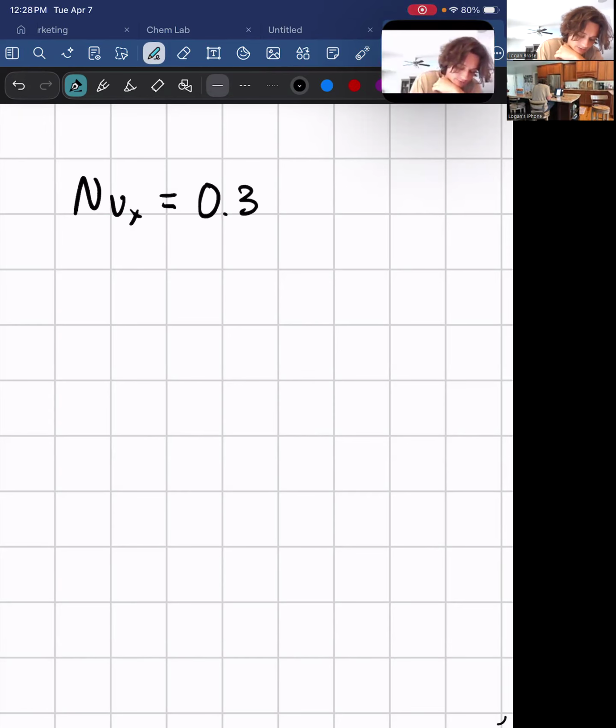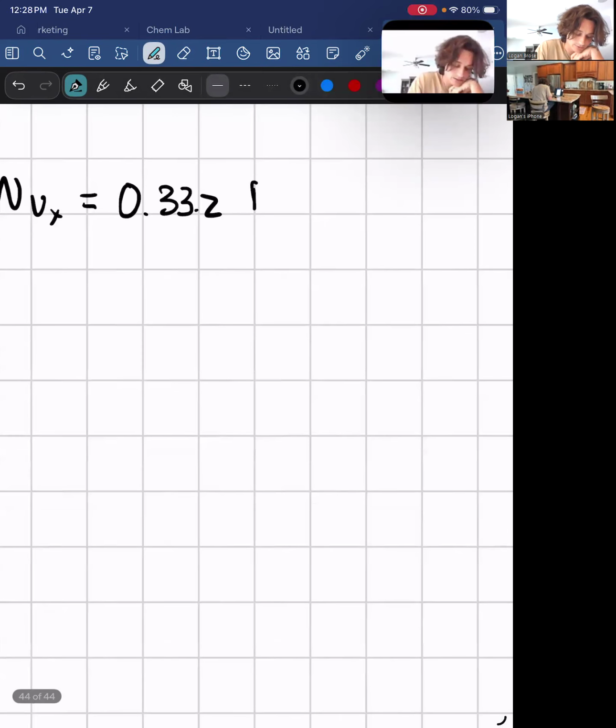All right, so this is homework 3, part B. We're going to be looking at the Nusselt number with laminar flow over a flat plate. In the x direction, the Nusselt number is 0.332. That's not 332. 0.332 times the Reynolds number to the 1/2 times the Prandtl number to the 1/3. So what does this mean?